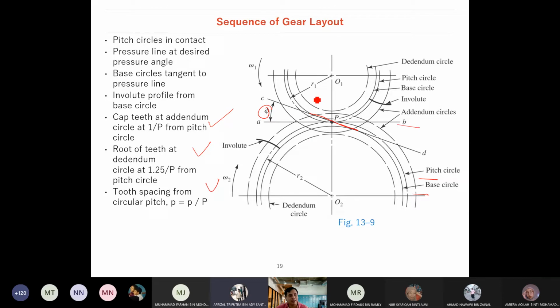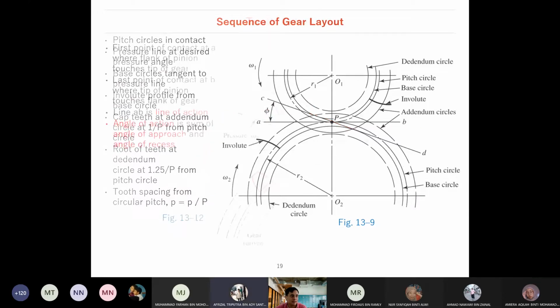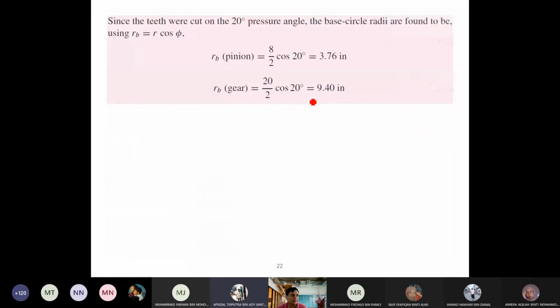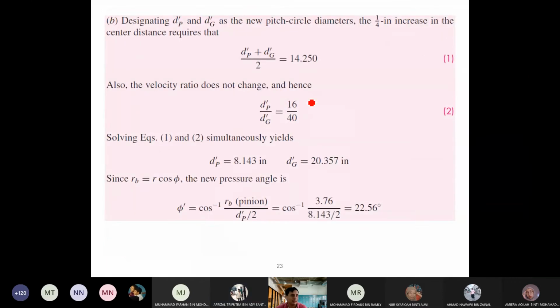So that you can reduce the interference. Interference is just advanced knowledge, I think. Basically, why are gear teeth 20 degrees and not 22 degrees? It's because of interference. Interference should be avoided basically.